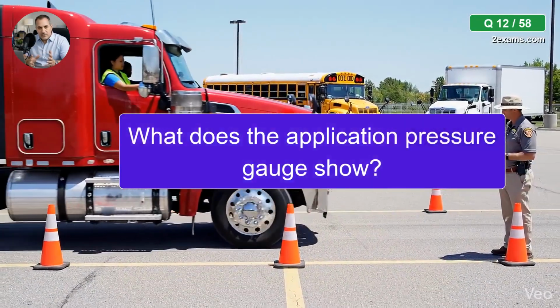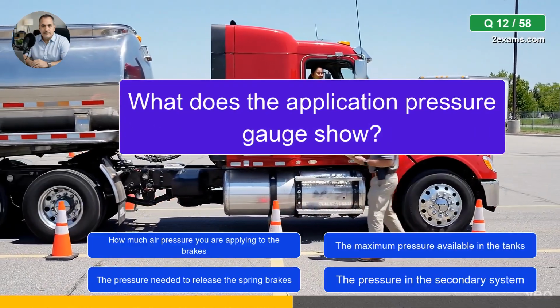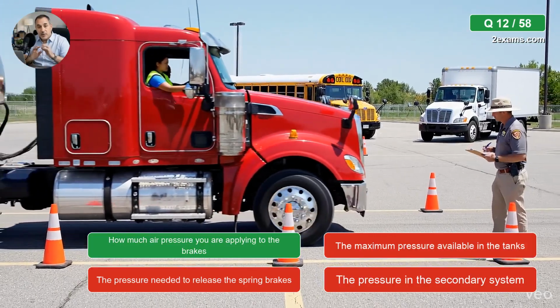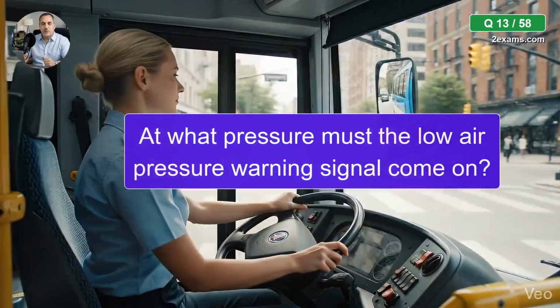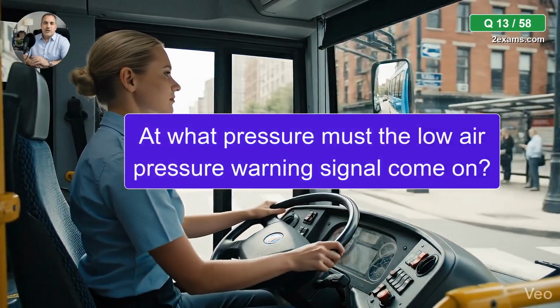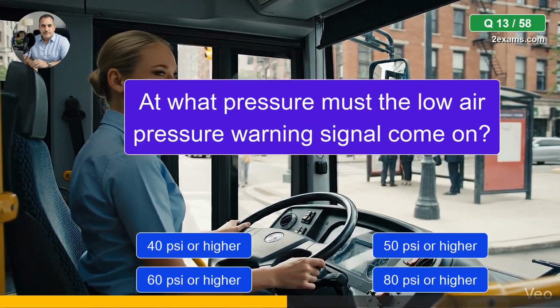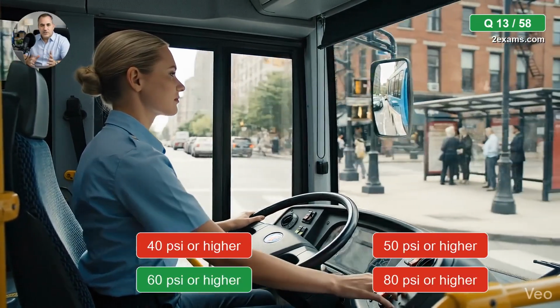What does the application pressure gauge show? The correct answer is how much air pressure you are applying to the brakes. At what pressure must the low air pressure warning signal come on? The correct answer is 60 psi or higher.